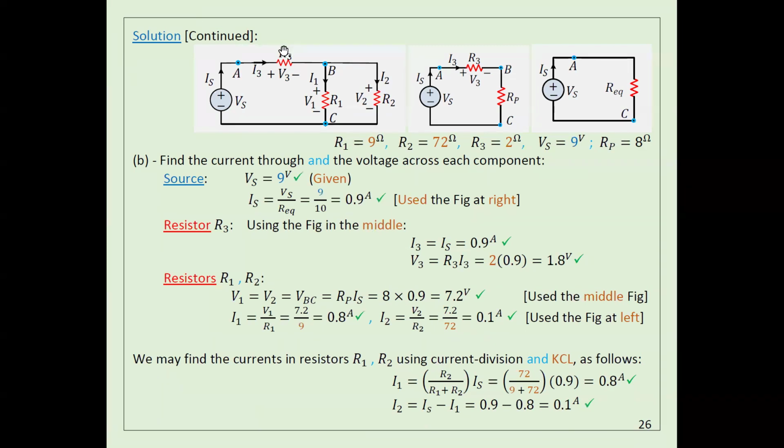There is another way. I just want to show you there is another way. Look here. The voltage from here to here, okay? I know the voltage from here to here, which is VS, is 9. So I have 9 volts here, okay? What is the voltage this one took? Okay, I think it's given, yeah, it's 1.8, okay? So here, total here, I have 9. This resistance took 1.8. So the remaining will come here, okay?